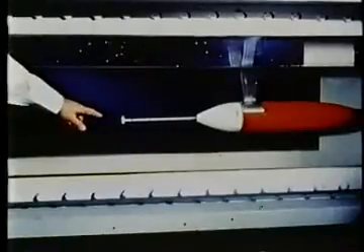Cavitation can also occur in turbulent shear flows because of the local pressure reductions in intense turbulent eddies. For example, let's look at the flow behind this circular disc. As the flow speed is increased, the pressure fluctuations in the zone of high turbulent shear lead to cavitation. With further increase in speed, the entire wake appears to be filled with vapor bubbles. Eventually, the flow becomes a true cavity flow, as distinguished from a cavitating turbulent wake.